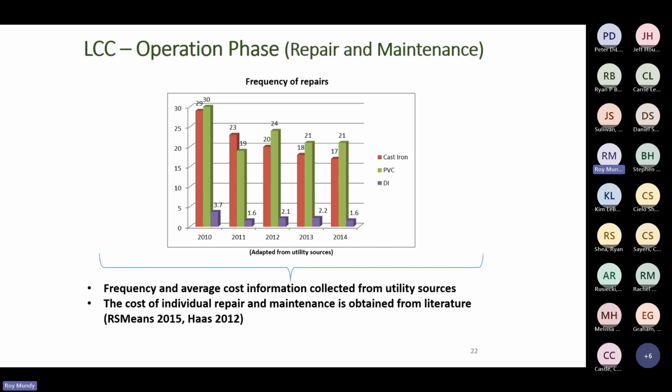And as you can see on the screen in the particular categories, effectively, the cast iron pipe did, in fact, show quite a bit of required maintenance and repair, but this pipe is probably already 80 to 100 years old. And so therefore it is nearing its life cycle end.